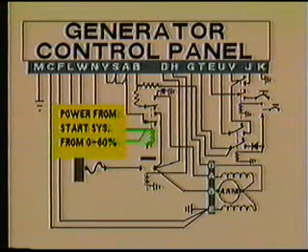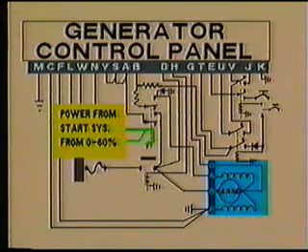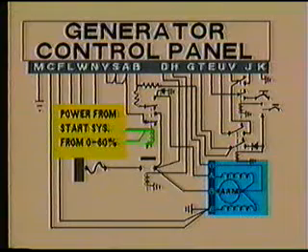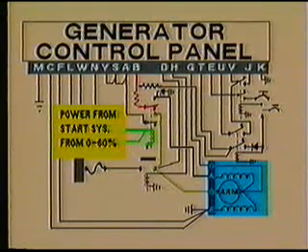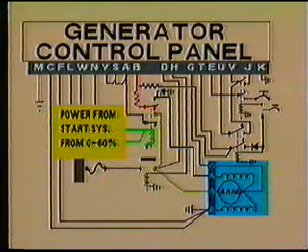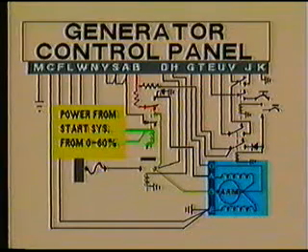The output control relay is energized during the engine start cycle between 0 and 55 to 60% RPM. Even though the starter generator is used as both a motor and a generator, it can never be used for both functions simultaneously. Significant damage to the starter generator and aircraft wiring could occur. To absolutely ensure that this condition never occurs, the output relay disconnects the field excitation circuit connected to the A terminal of the generator and disconnects the control panel connection of the generator B terminal as well.